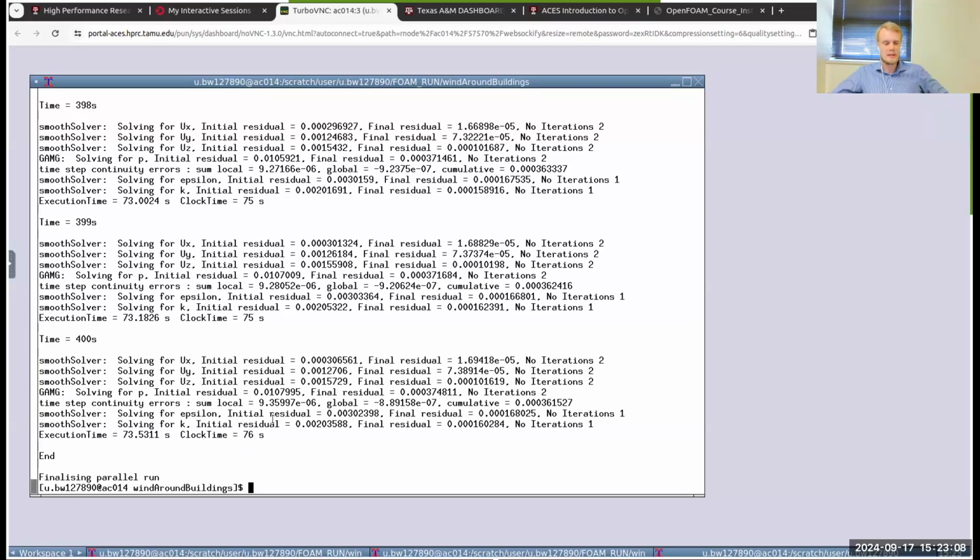And these commands, because OpenFOAM is all command-based, as you will have noticed by now, lend themselves very well to writing fairly easy to read job scripts that you can submit to the cluster. You would just type all of these commands that I've been typing manually into a script, and then you submit that script.